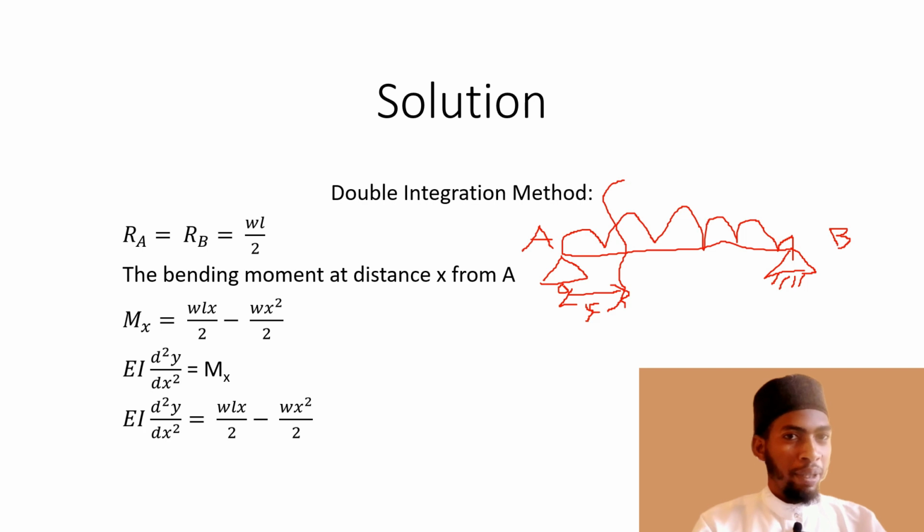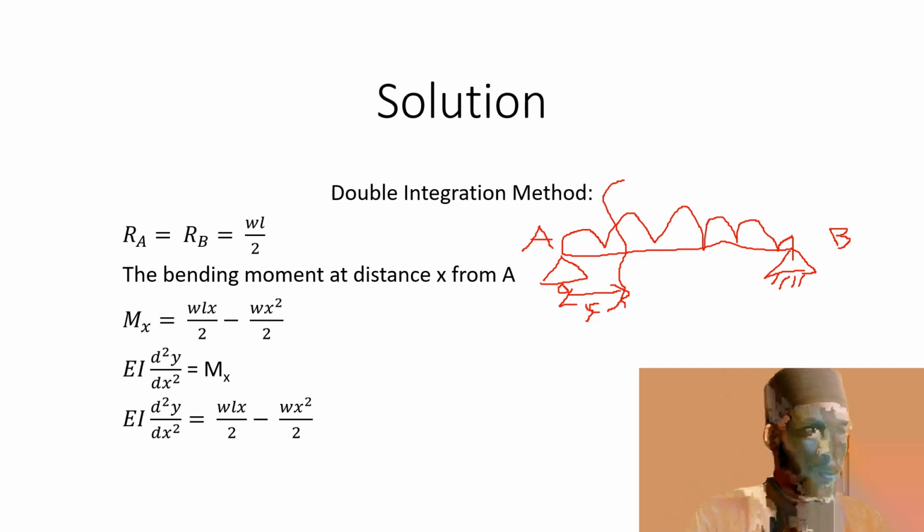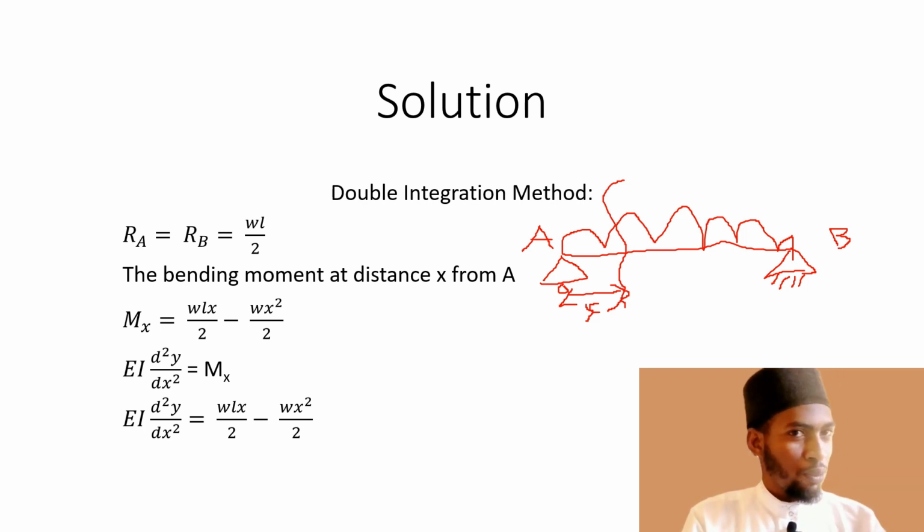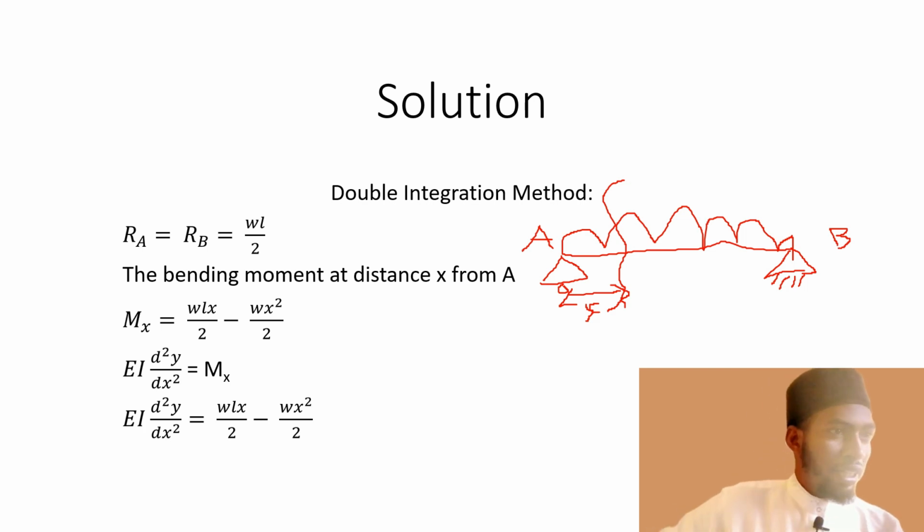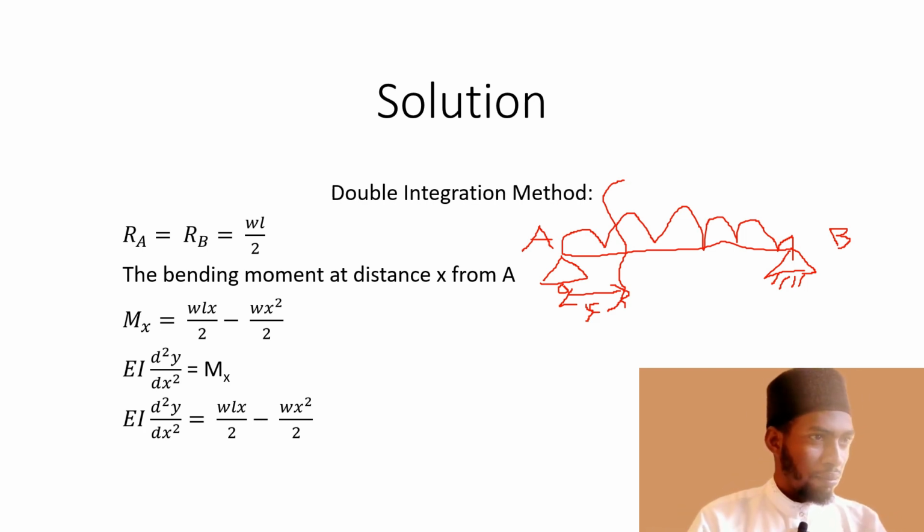If you remember in our strength of materials course, what we adopted as our sign convention is when you are coming from left, clockwise moments are positive. From right, clockwise moments are negative. So if you look at this, we are starting from left, that is from support A. If I am to take moment here, definitely it is going to be a clockwise moment, because this force is likely to push this section to rotate in a clockwise direction.